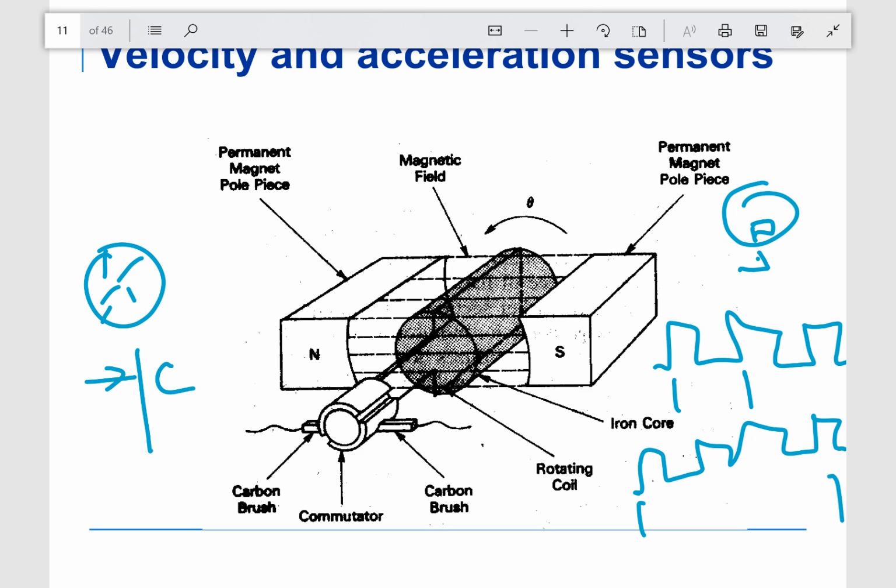And this will talk about the Hall effect here in a minute. But we can either use light through a slotted wheel, or we use the Hall effect. Most industrial applications are using the Hall effect simply because of the light in these wheels. The amount of dirt that clogs up these windows sometimes gets to be a problem, so they have to be kept relatively clean. They manage to collect dust and fill up with dust.